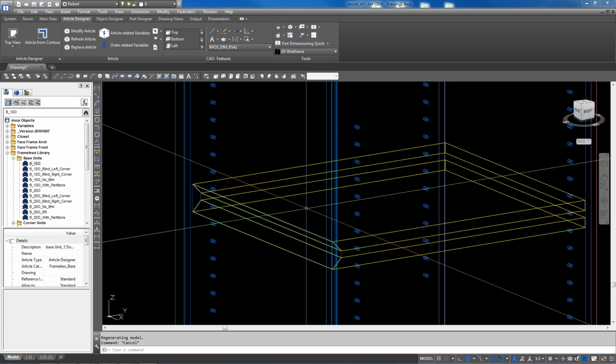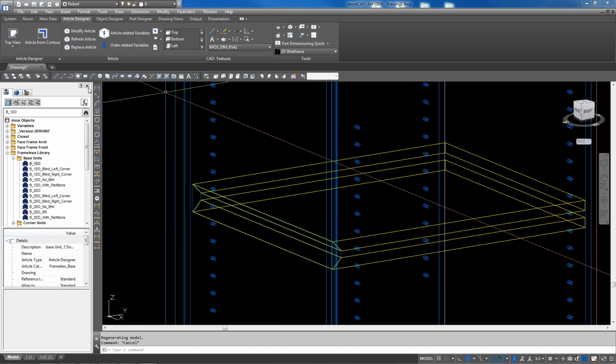Oh. So you're not going to actually cut 3 separate parts. You want to miter fold them together, correct? Right. What we've done both ways so far just cuts 3 separate parts. Now we want to actually miter fold them together. So the miter fold trigger is located in machine information. So let's go ahead and modify the article. We'll start with the top.